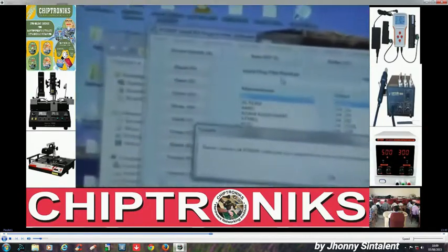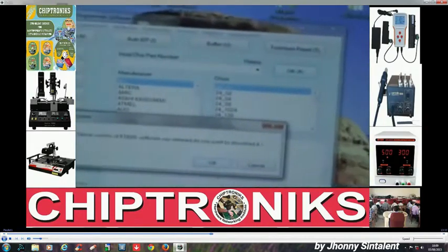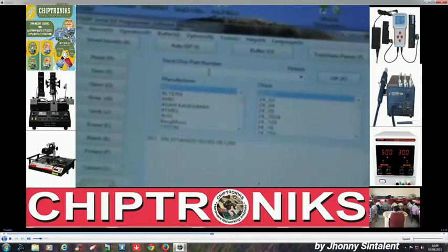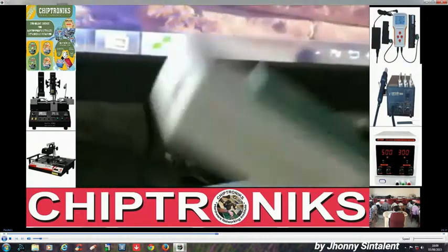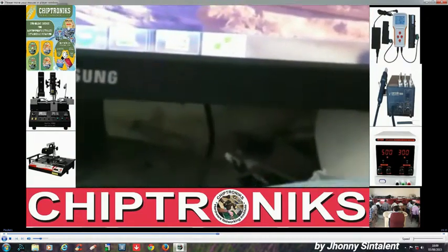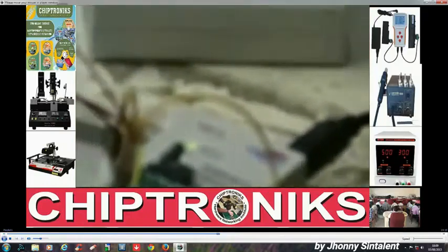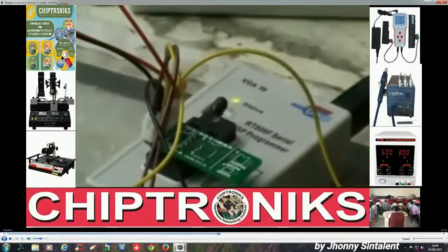If I type 9012, it will show you KB9012QFA3, and this is the most important thing. This programmer has a facility to diagnose this chip, whereas the TL866CS programmer doesn't have such a function. That's why we are using this RT809F to flash the embedded flash.